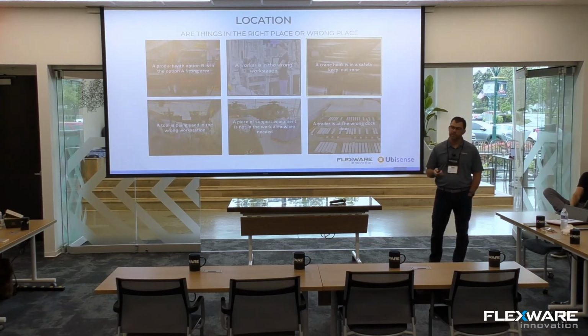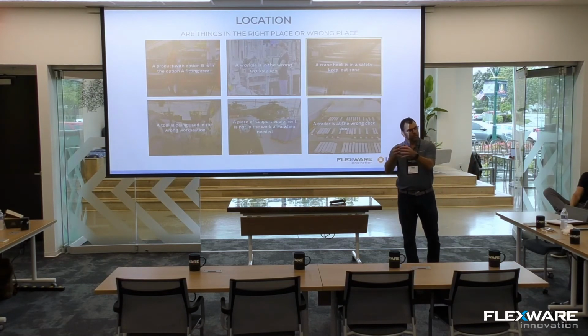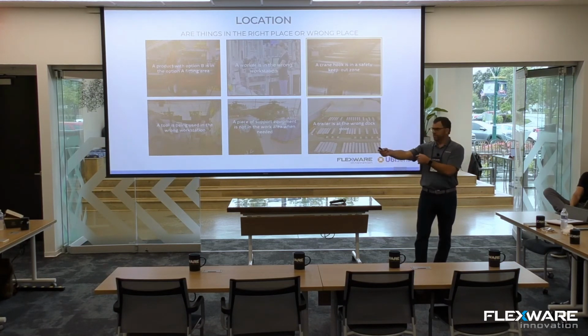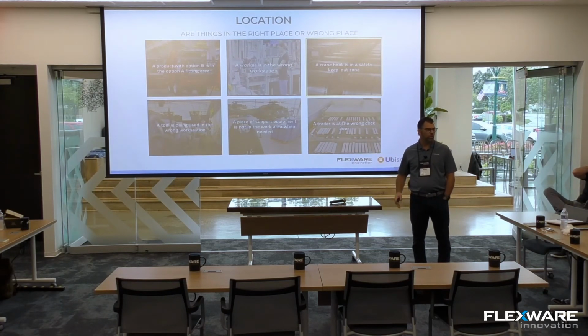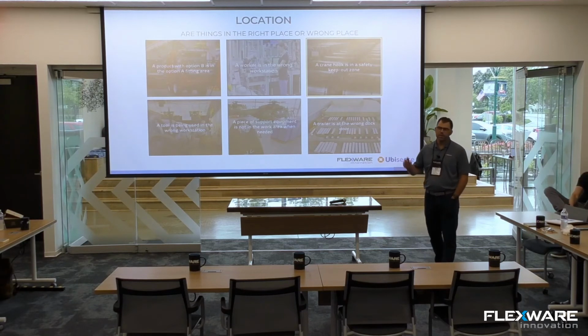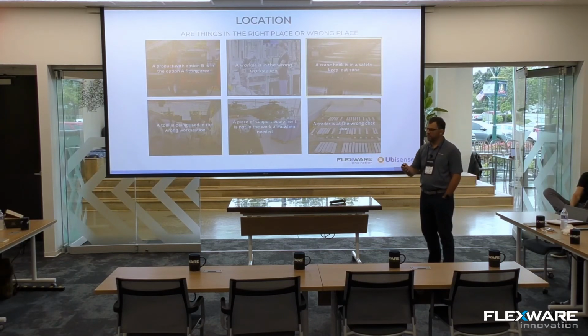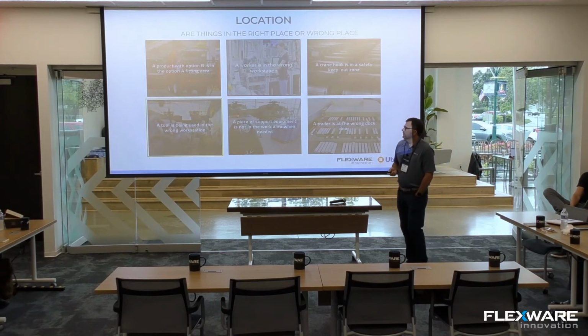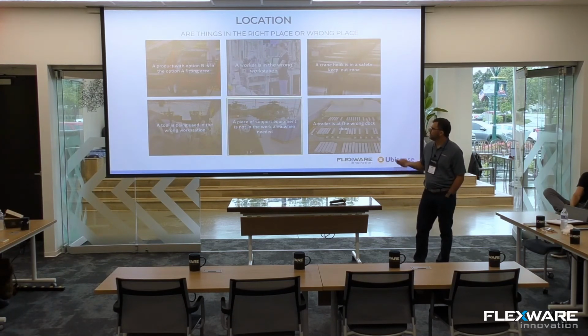We do a lot of things called process interlock, where lines pulse and big machines move. Well, if there's crane hooks and assisted lifts that are still over in the pulse area of the equipment, guess what? Those get hit, those get taken out. So we can track those and make sure they're back in a home position and send that information to the control system, MES system, prior to a machine pulsing. A tool is being used in the wrong workstation. Piece of support equipment is not in the work area when needed.